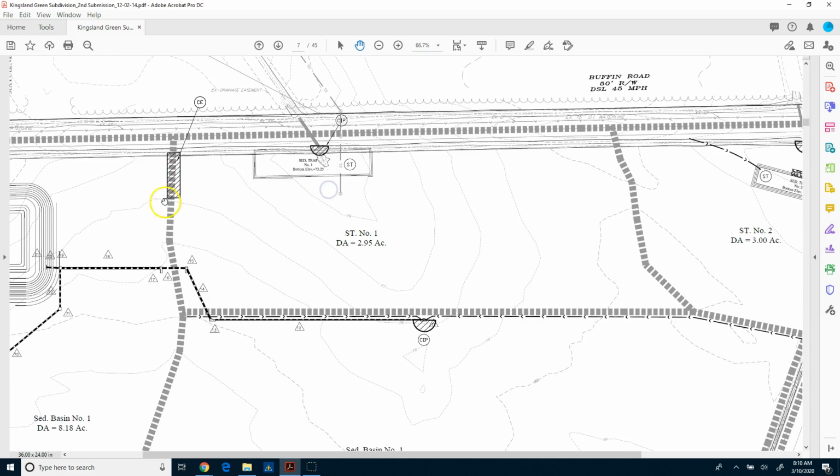first thing that you'll see, these big thick lines is basically what they're called drainage areas. So this area, if any rain fell within this area, just by the natural state of the ground, it's going to drain to this sediment trap. So this happens to be, looks like, a culvert crossing here, and they're putting in a sediment trap here to catch any of the runoff, and therefore all the sand and silt will settle before the water continues on downstream, and that keeps the sediment on site.